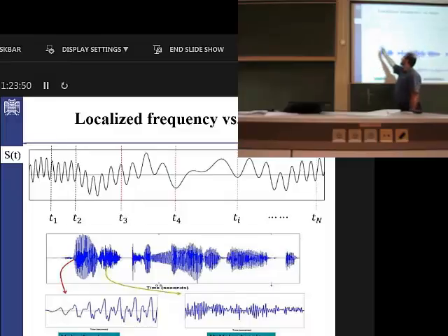If you look at the signal at this moment and only at this moment, what you will get as information is a periodic signal, a sinusoid, with the frequency of whatever is between these two peaks. That's the only information you get. If you move that to the frequency domain, you will just get one impulse. Nothing more. It seems that this signal just contains one frequency.